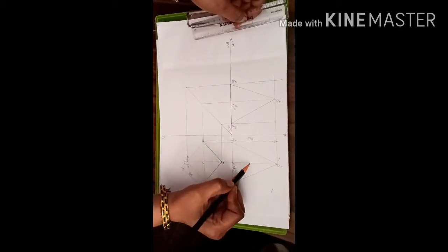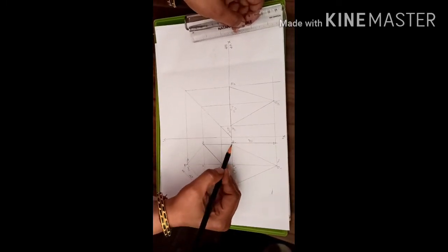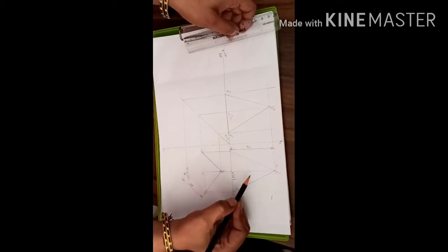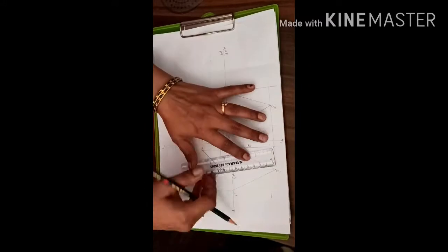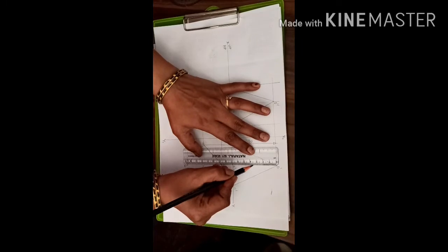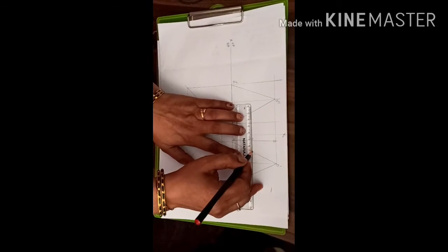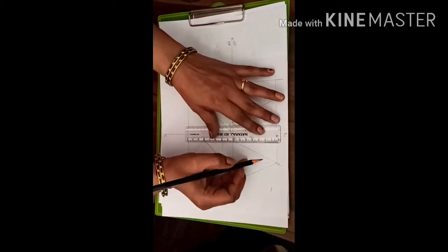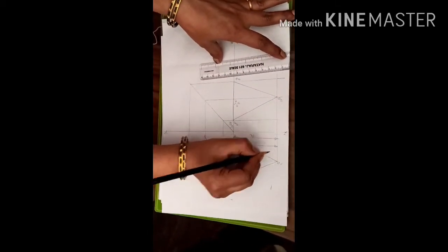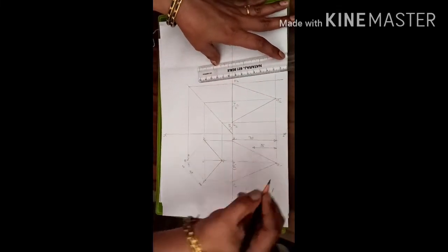So we shall find out the midpoint of the axis. So definitely, since the height of the pyramid is 70 mm, the midpoint lies exactly at a distance of 70 by 2. So I shall measure 35 mm from its apex. So 35, I get the 35 mm line here. So I'll just show that this distance is how much? This distance is 35 mm. So your axis line is to be bisected. So therefore I write this as 35 mm.